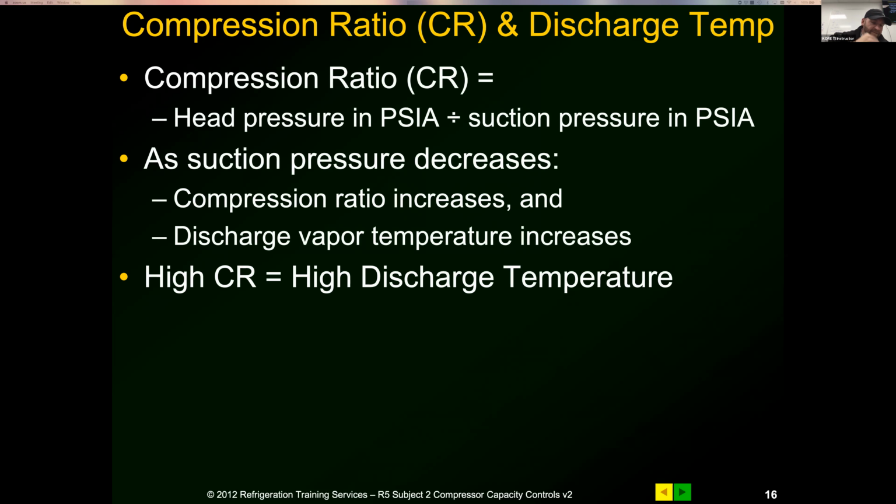So you're picking up heat. From the time that your refrigerant leaves your metering device, your TXV, it's in absorption mode, so it's going to continue to absorb heat. The superheat measurements we take are to measure how much heat we're absorbing. That's why when you're taking superheat measurements at the evaporator, you're measuring how much heat pickup or heat transfer you're having at the evaporator. When you're measuring at the compressor, we still need superheat. We still need heat transfer properties in order to absorb the heat in the compressor through the heat of compression, and so it's still in absorption mode.